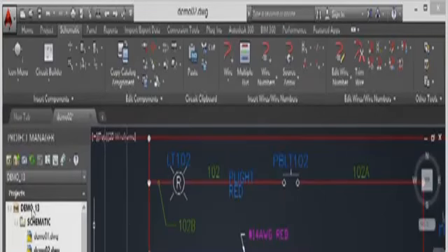We're still in the Demo 13 project, and again, we're in the Demo 02.dwg. Now we're looking at these lights here. We've got LT102, LT105. Now if I hover over LT105, all the attributes highlight there, and you can see that that power on attribute is part of LT105. LT102, you can see that P light red, the description, is also an attribute of LT102. So let's have a look at moving those attributes and tidying this up a little bit.